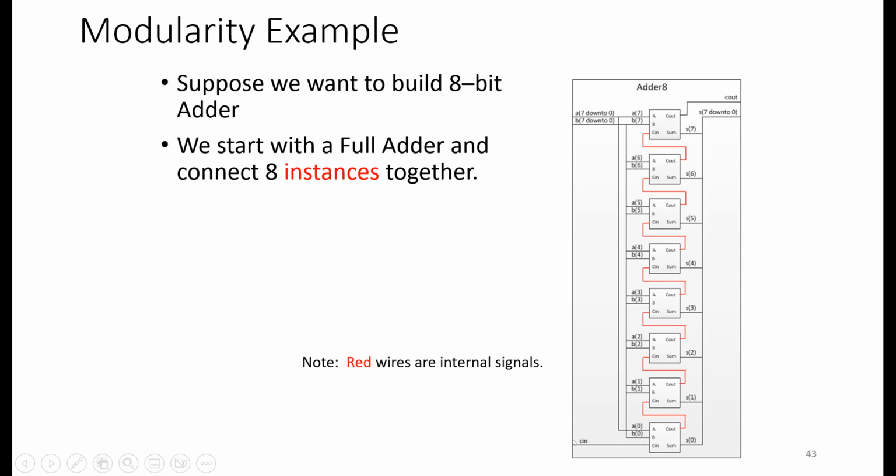In addition, I have carry in from the previous stage, if there is one. If there isn't, as our case, I will make it 0. But each full adder will have 3 inputs. So the first one, I need to feed it with 0.